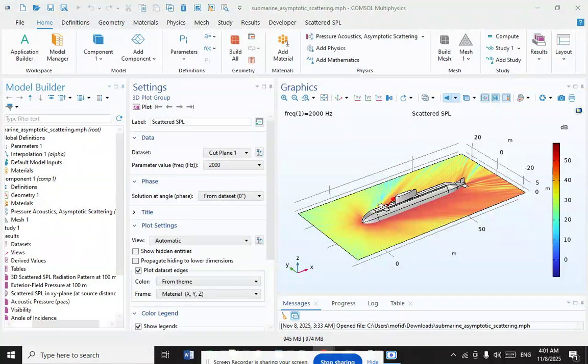The hybrid modal method gives very accurate results but is limited to cavities which are made up of sections of uniform waveguides for which the modal fields are known. The GO ray shooting method can be applied to much more arbitrary cavity geometries and can handle absorber-treated interior walls, but it generally only predicts the major trends of the RCS pattern and not the details.